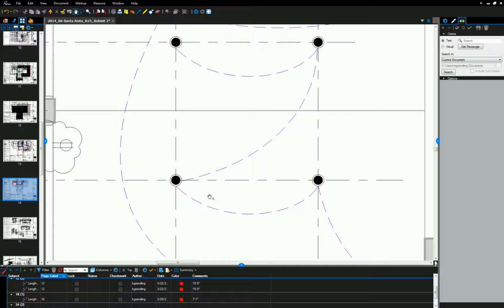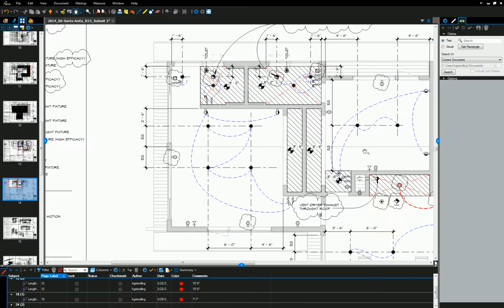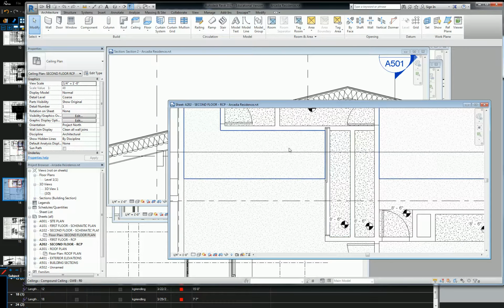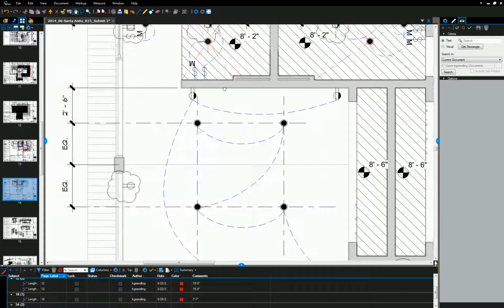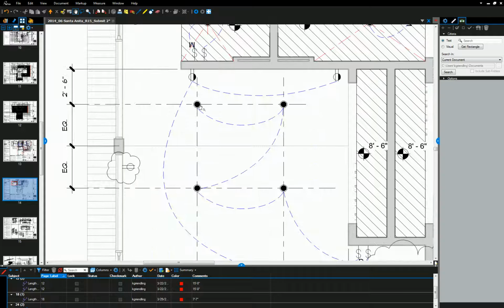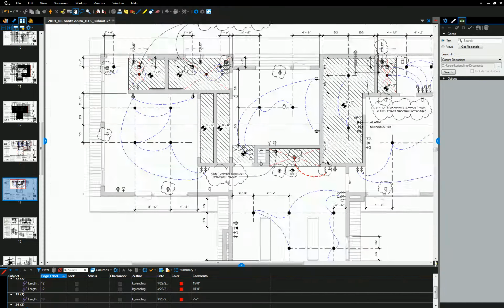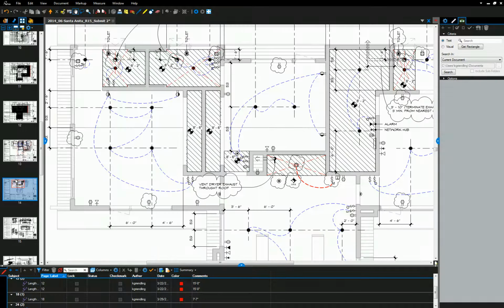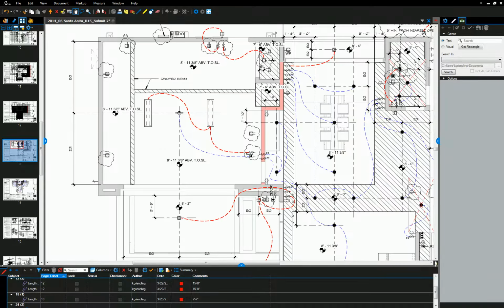So we're just going to place lighting fixtures on the face of the surface, but we're going to try to align them so that they're along these lines. Let's start by loading lighting families, and we're going to need two primarily. I'm just going to stick with whatever we have here, which is most likely a recessed can downlight. And then we're also going to do a strip light, because on the first floor there are these strip lights, which I assume are pendant lights. We're not going to get into too much detail on those either. It might be a troffer light, not sure.